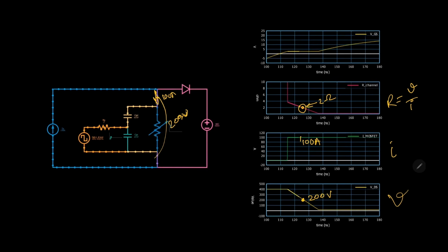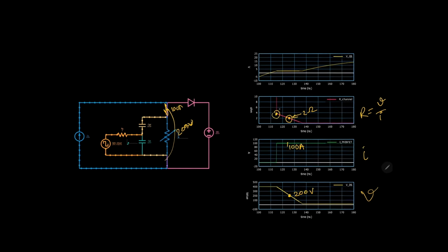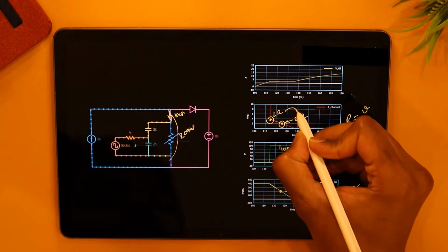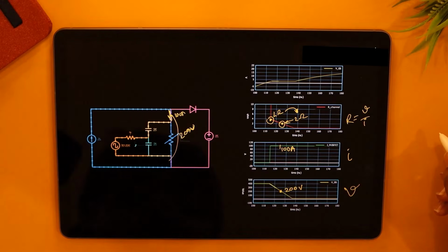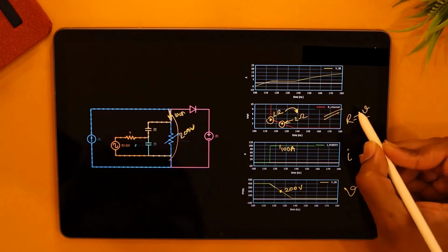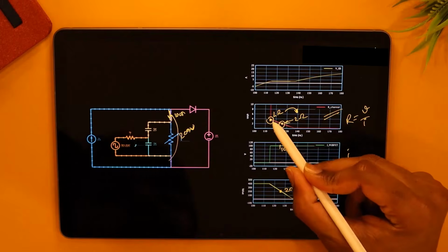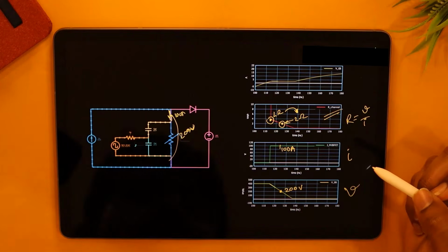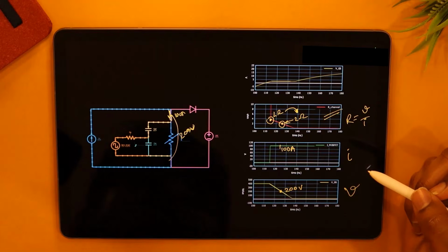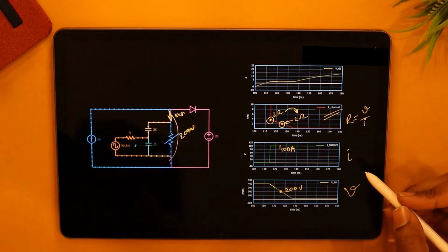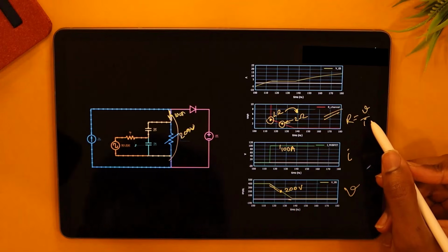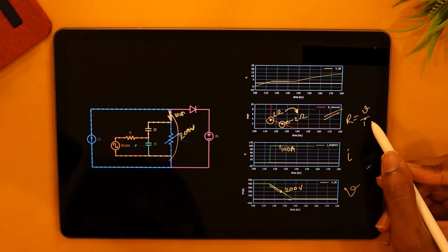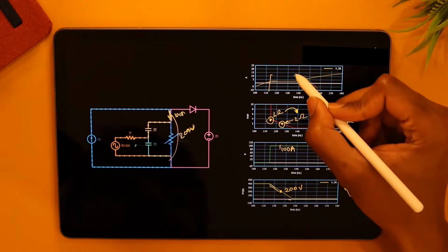I mean, we started the plateau with the resistance of 4 ohms, and now we have dropped to 2 ohms. What's happening here? We thought during the plateau, only CGD is discharging. But there's something more at play here. The MOSFET is effectively turning on slowly. Look at this resistance waveform of the MOSFET. It's dropping slowly. It's turning on slowly during the plateau region. I think it makes sense. I mean, during the plateau, the voltage is continuously dropping. Current is the same. So, of course, the resistance has to drop. The MOSFET is slowly turning on as the CGD is discharging during this plateau region.